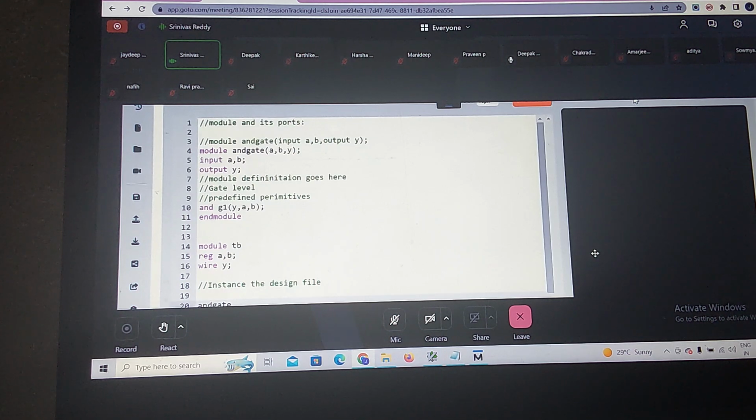You can write UUT, meaning unit under test, or you can give any name, your name also. You are putting your model to the test. Correct. So I am going to write DUT, followed by parenthesis. Now we need to do the port connections.